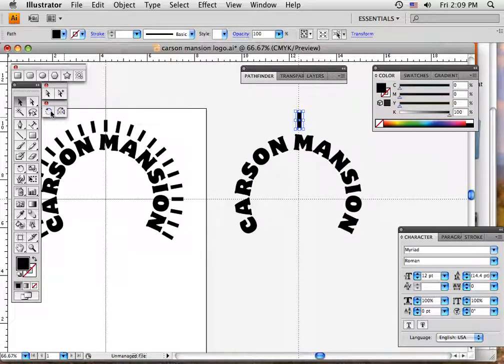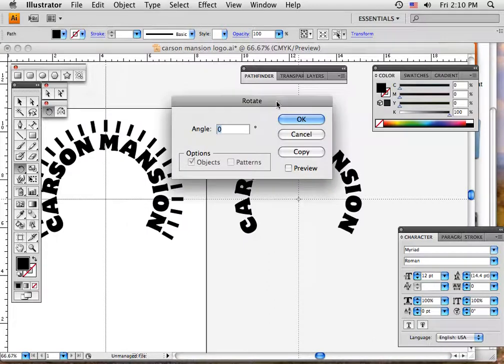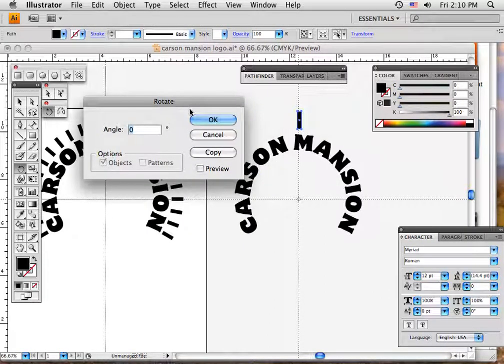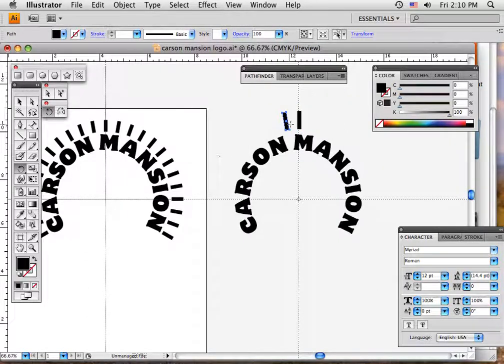And then I'm going to take my rotate tool. Now remember that's selected there, but you bring your tool down here to the crosshairs where they meet in the center point of reference, and hold down the Option key and click once. Now you have to come up with an angle that you're happy with that divides into 360. I'm going to use 10. That's not a very wide thing, so I'm going to say 10 and hit copy, and it puts, you know, a little gap there.